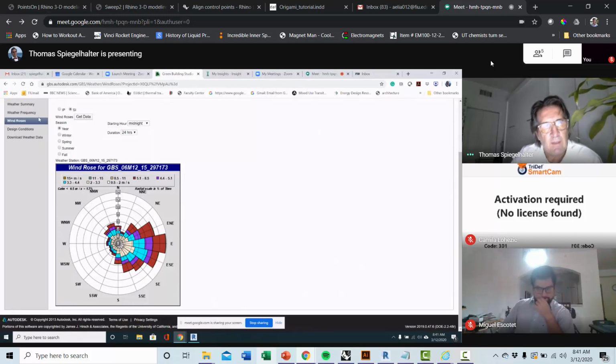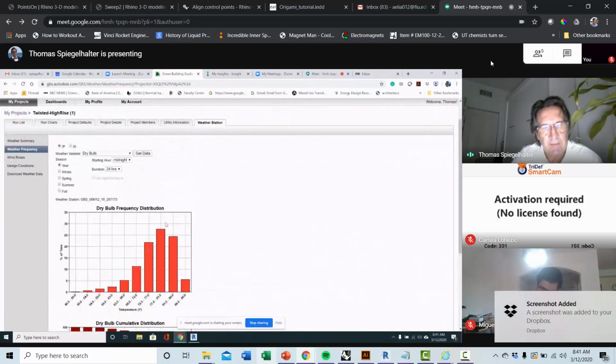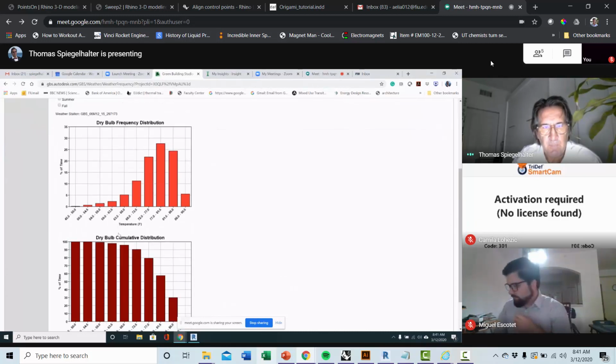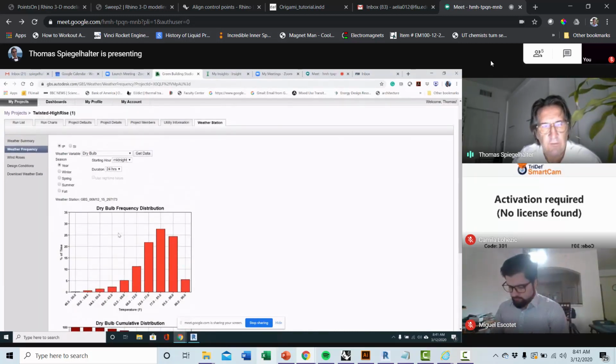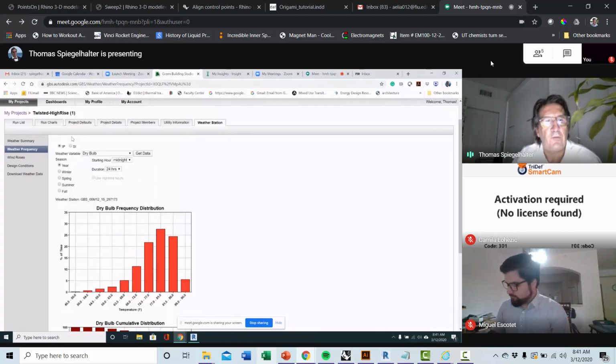Now, these data sets are very important for you in terms of setting the baseline templates in the wind tunnel in Autodesk Flow or Autodesk CFD or any other Revit compatible computational fluid dynamics software that needs to be related and referenced to this weather station ID and data. You cannot skip this, otherwise all the flow and CFD simulation you perform are completely useless because they do not have any reference. They have no quantification, they have no evidence. So make sure you have that.